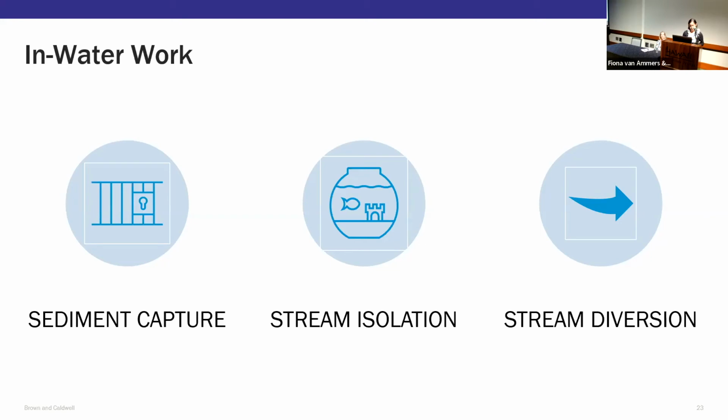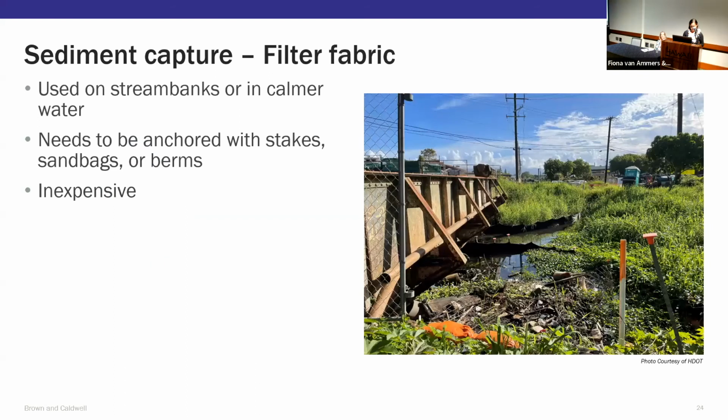First, we're going to go over sediment capture. So there's a few technologies for sediment capture, which include perimeter erosion controls, turbidity or silt curtains, and sediment traps. Perimeter controls like filter fabric are fairly good in calmer water and relatively inexpensive.